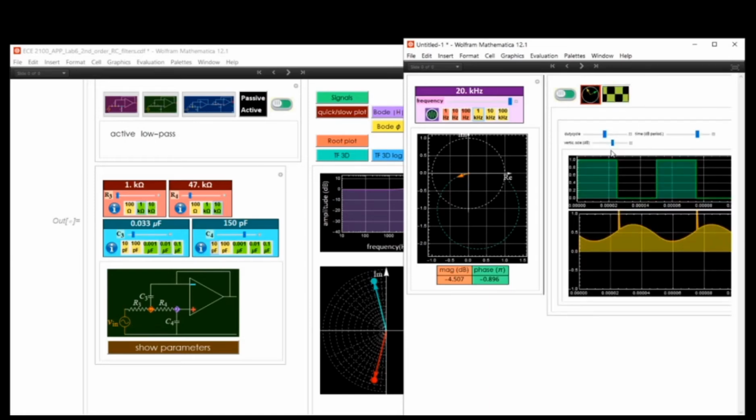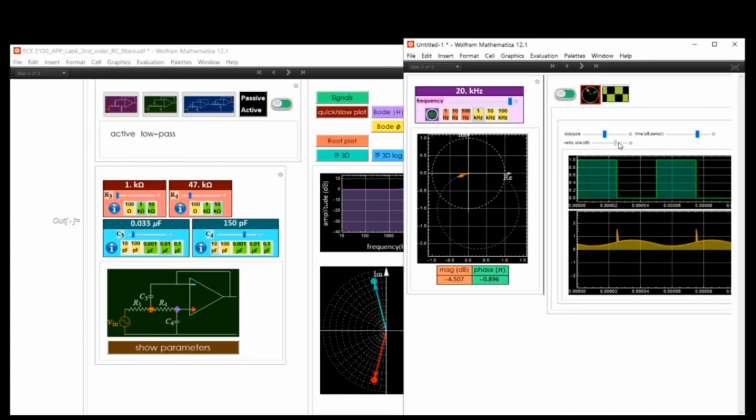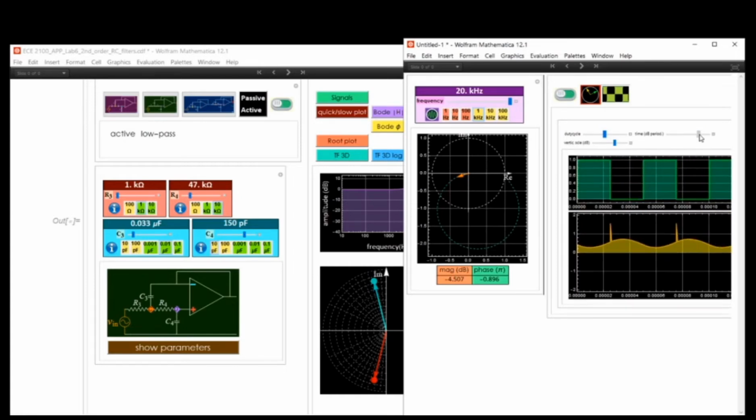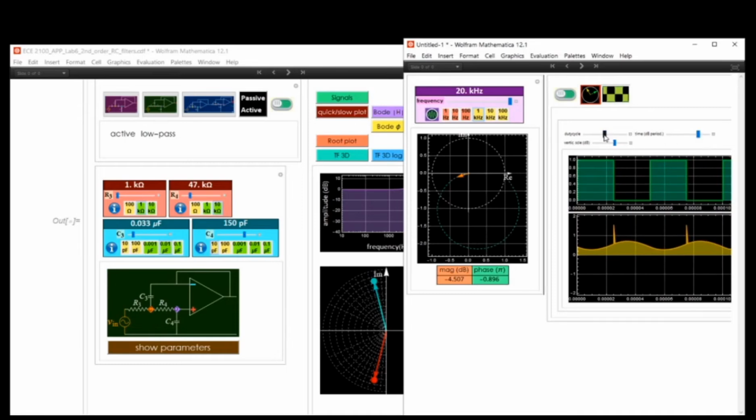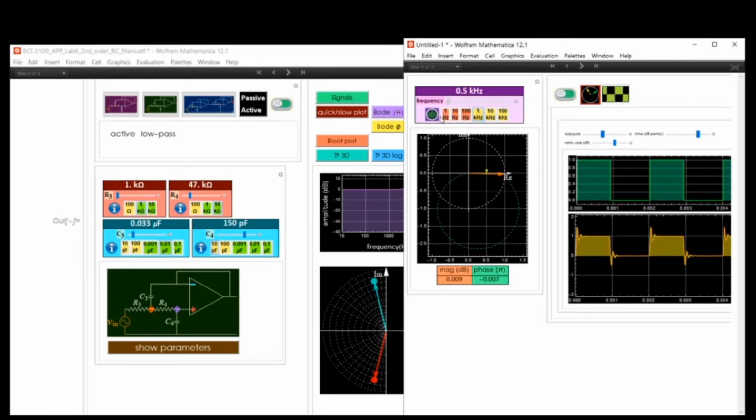Step response to a square wave input is also a useful check. Select a square wave period that is much longer than the damped oscillatory response of an input step. This response is what caused the spikes observed in the various demonstrations of the use of this filter for communication signals with noises and interferences.